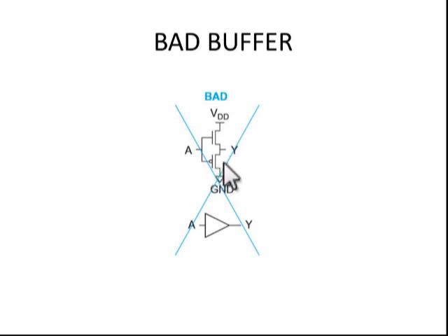And again, here the PMOS is connected to ground. So when this PMOS is on, now this 0 is connected to Y. Actually, the PMOS has good 1 and bad 0. So that means we will get degraded output. So in both cases, the 1 and 0, we are getting degraded outputs.